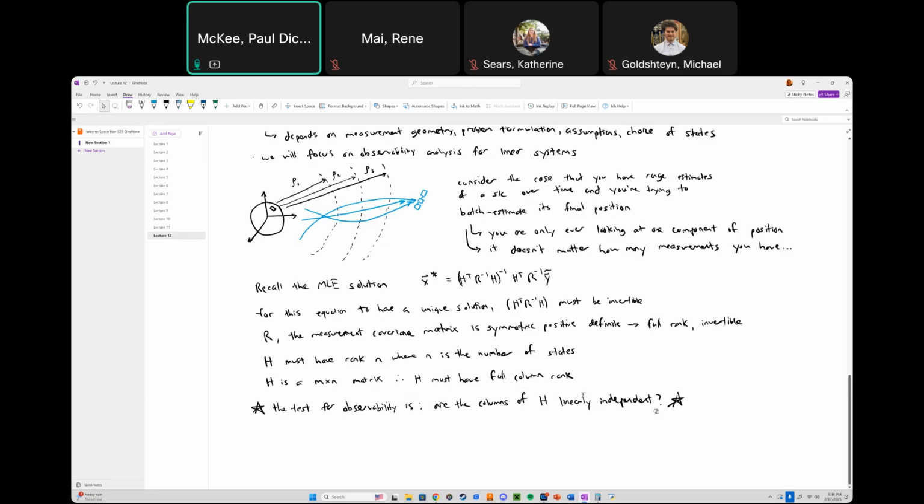So we want to be asking ourselves these questions. Later in this class, we're going to set up a sequential estimation problem where you have range, range rate, and bearing, and you have those over time, which does not give you the full 6 states of your vehicle, but enough of those over time is enough to pin down the full 6 states of your vehicle. So in a batch or sequential estimation problem, that is enough, even though you're never directly measuring tangential velocity of the vehicle.